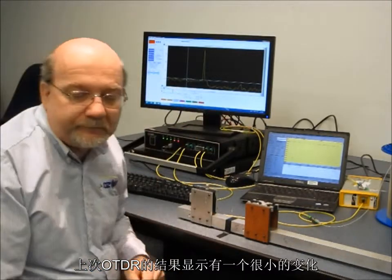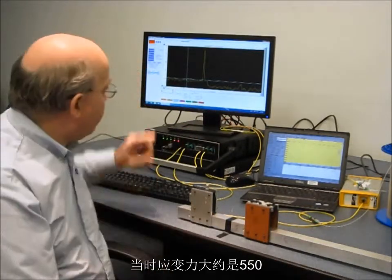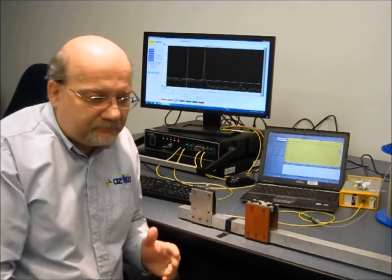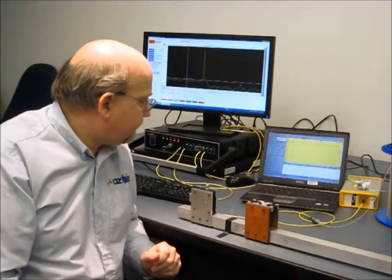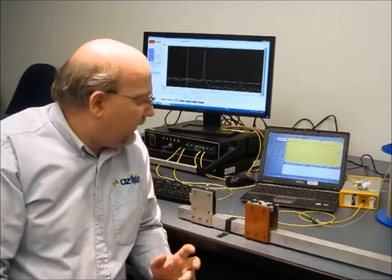So as you recall, before we had a very small change on the display from the OTDR when our strain level was about 550 microstrain. Now that we've cut it down to half, will we be able to see anything at all? Again, it's taking about 60 seconds to record the results. So we just have to wait until it's done.